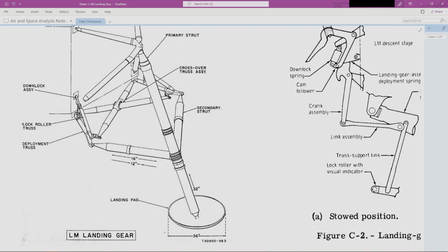So this section is in bending, and this section a bit too, because it'll tend to bend around this point and be reacted up here. But generally it's in compression when you land, right? Compression goes up the strut like this. And then this is actually designed to be a honeycomb crushable.